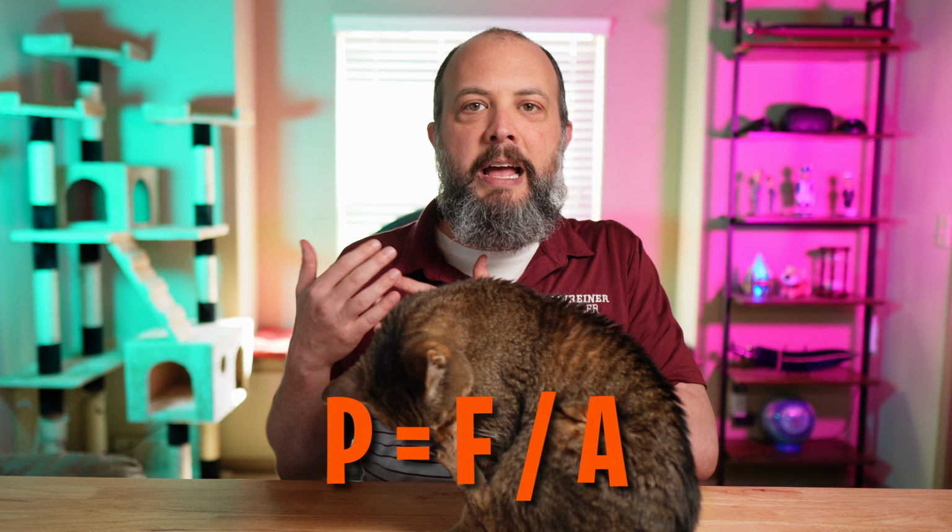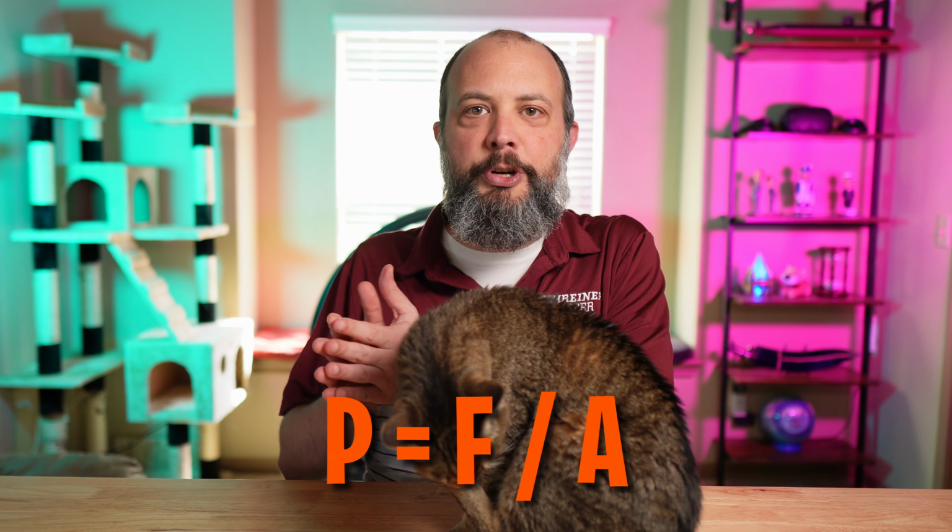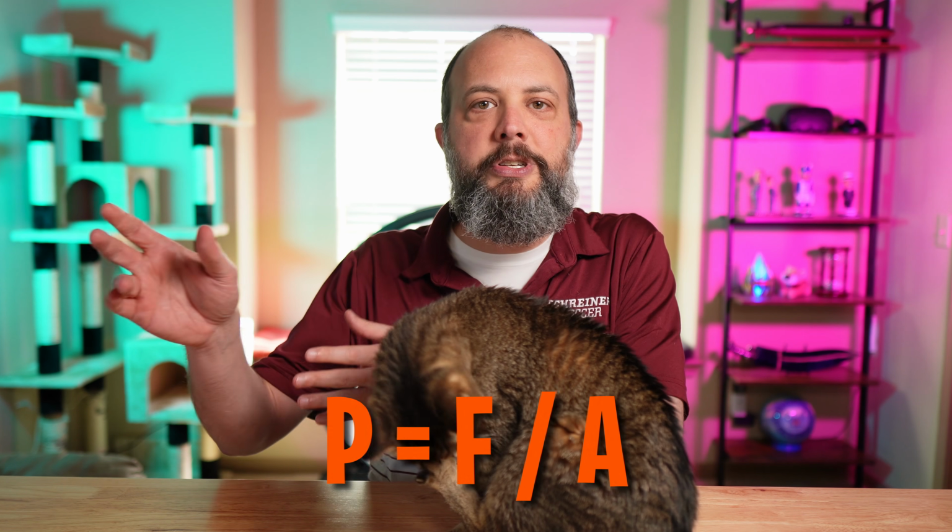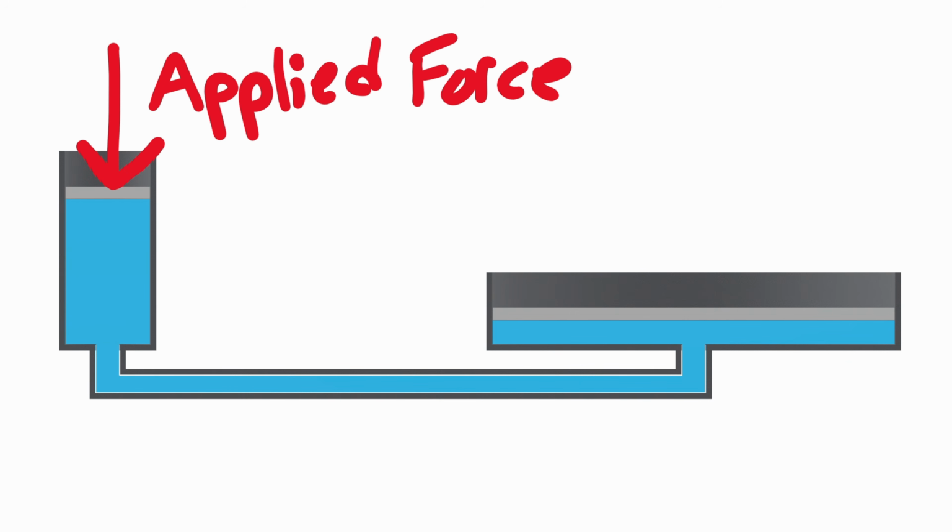In hydraulics, mechanical advantage can be explained through Pascal's Law, also called Pascal's Principle. Applying a force to a contained liquid creates a pressure as force divided by area. And that pressure is immediately transmitted to every surface in contact with that fluid. So for this drawing of a hydraulic lift, applying a force on one side creates pressure that pushes outwards on every surface: up, down, left, and right.